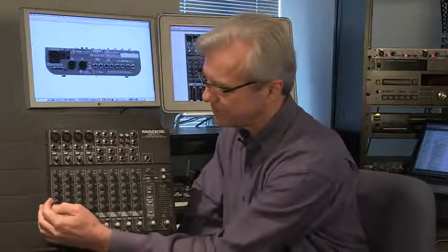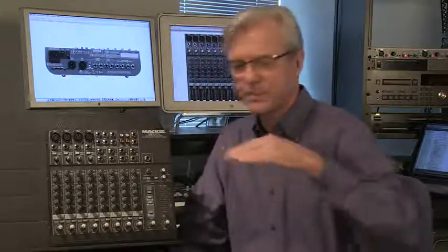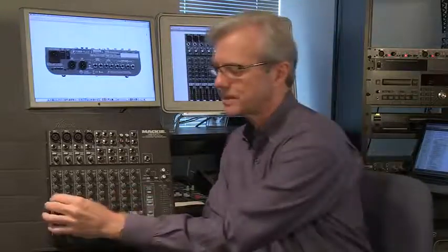What we have here is a three-pole equalizer. So in this one we have a low frequency which is set at a mid-range of about 80 hertz. So when I am amplifying or attenuating using this, I have set a center frequency of about 80 hertz, and then I have some range on either side of that. And that range is being preset in the mixer. I can't control that. But what I can do is either attenuate or amplify everything around 80 hertz, which is going to be your low-end bass frequencies.